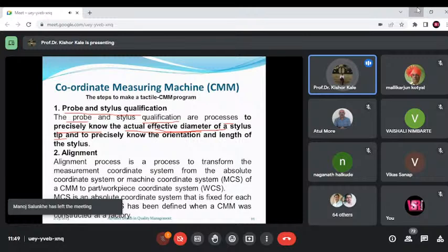So what is the problem with this? A is the manufactured surface, and B is the nominal surface, that is the CAD model. So what is expected? Suppose this is the distance between the two. This is the shorter distance method, the ICP method.